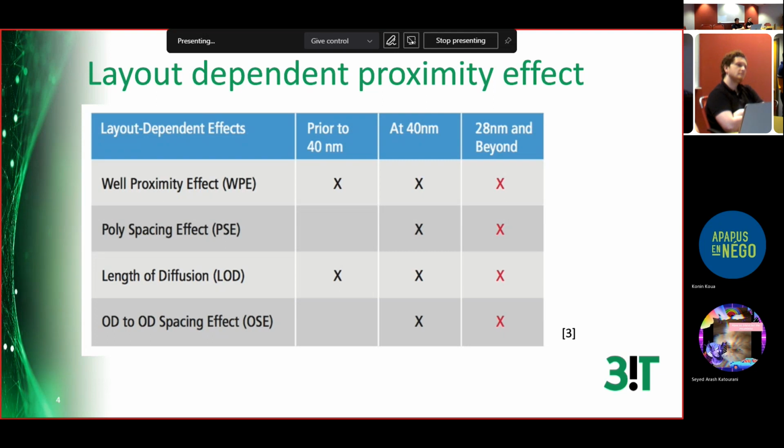Because, as I said again, for matching, what is surrounding your device impacts its performance. You can see it as a building or anything: whatever is close affects or creates some stress on its neighbor. At this distance X here, there is one amount of stress that everyone sees. If it's different, it will be a different stress. So when matching matters, you need to see exactly the same stress.